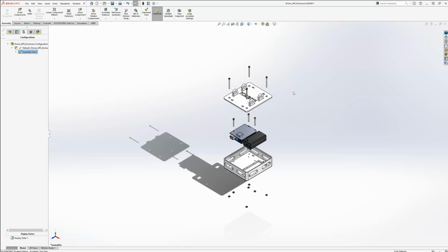But now that we have the exploded view, we're saying, hey, I want to use this as a start point to create an exploded view in a 2D drawing, and I want a nice table down there that'll have the BOM, so that it says things like, hey, when I've got these 4 different socket head cap screws, that they're all 4 the same, so that way I can go to a fasteners type store, Fastenal, for instance, and buy the screws I need. And so that's what we're going to do. We're going to basically take this assembly view and put it inside of a drawing.